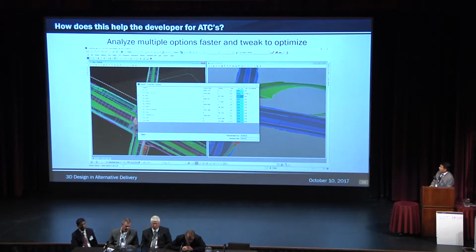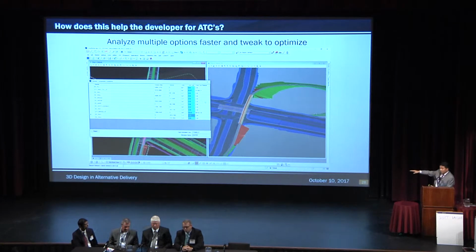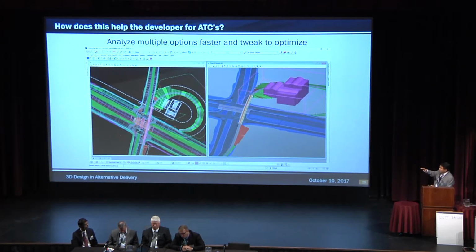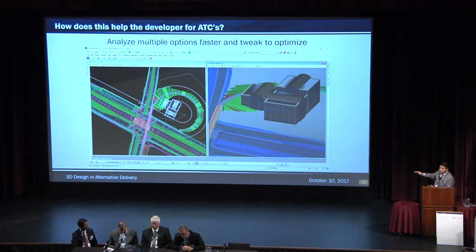quantities. Now, there may be big differences because in my template, I created a bunch of rules that say I'm going to go down from the edge of pavement, go down at a 6:1, and if it goes past my constraint lines, my right-of-way lines, I'm going to go down to a 6:1, 5:1, 4:1, 3:1, 2:1 retaining wall.